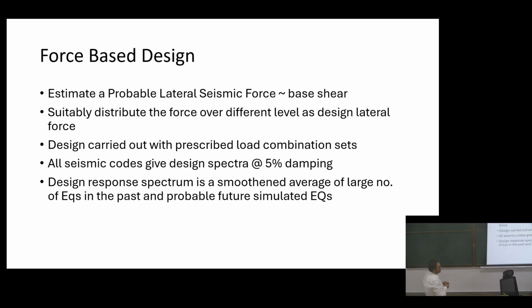The design response spectrum is a smoothened average of a large number of earthquakes in the past, because we have the ground data for them, and probable future simulations of earthquakes, because we don't know how the ground will shake in the next earthquake. So those are probabilistic simulations of the future earthquakes in that region, with the history that we have in our knowledge bank of that region and how it'll behave.